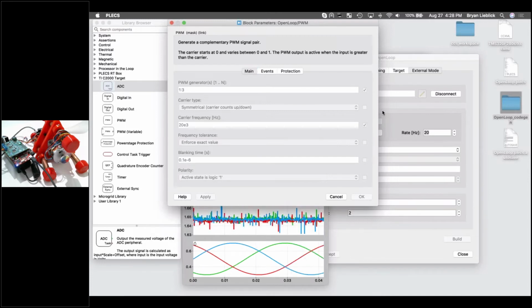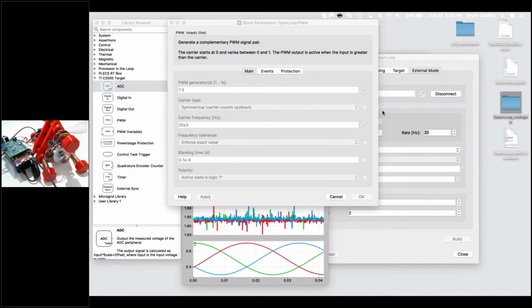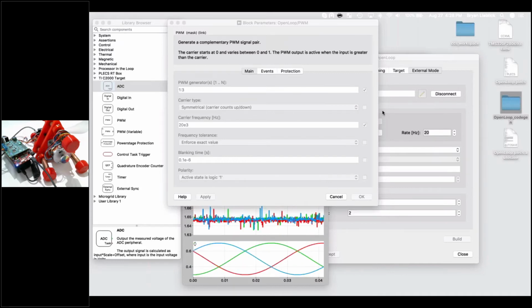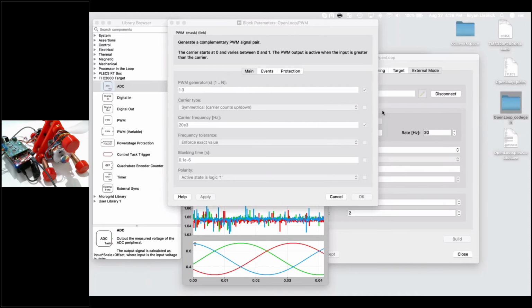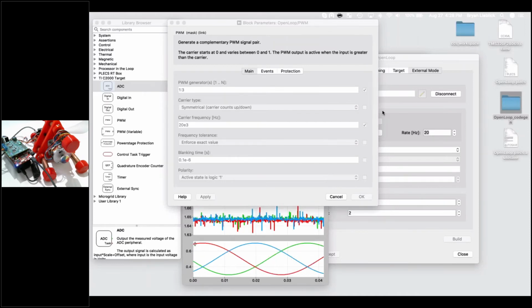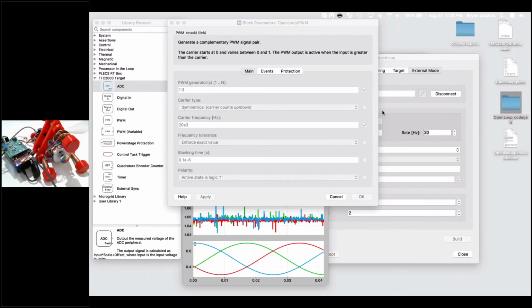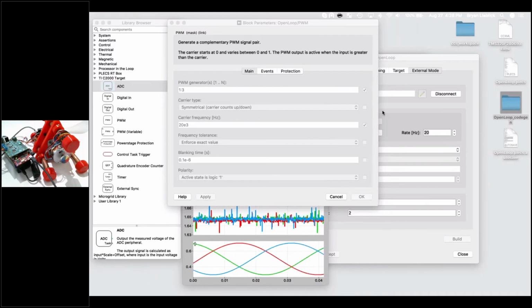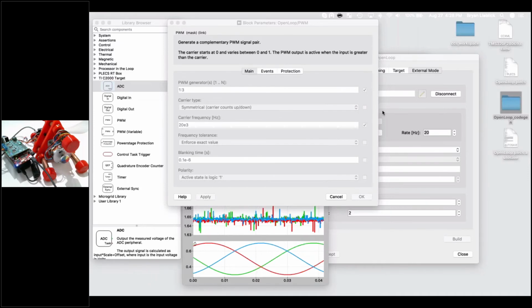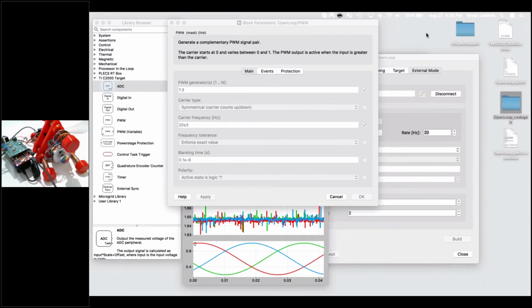Sure. Yes, you're making a very good point there, James. The timing and the synchronization of events in power electronics systems is hugely critical. Often switching frequencies are high, time constants are relatively small. So it is important that measurements are taken at the right time and that the PWM duty cycles are updated in a synchronized fashion. So what we have introduced with the latest version of PLECS and the first release of